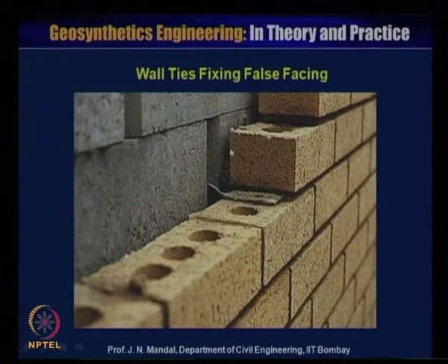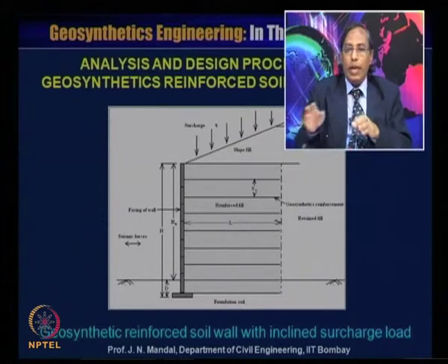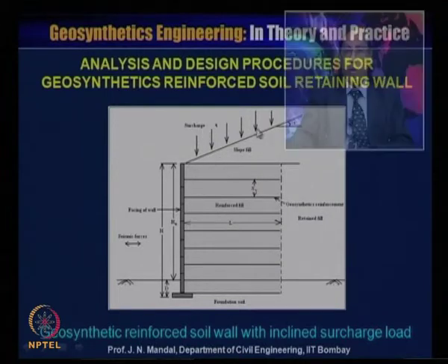You can see wall ties existing, provided with the false spacing element here. So now we require the analysis and design for a geosynthetic reinforced soil retaining wall. These are geosynthetic reinforced soil walls with inclined surcharge load. Sometimes it may be inclined, sometimes it is not inclined. If there is an incline, then you have to consider what will be the surcharge load.